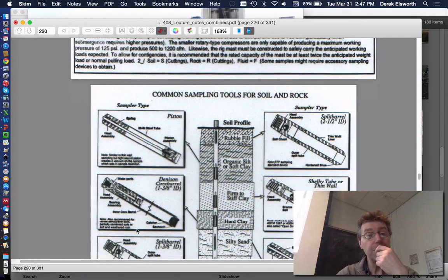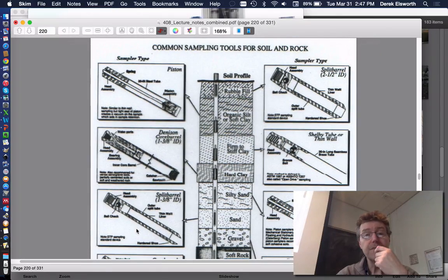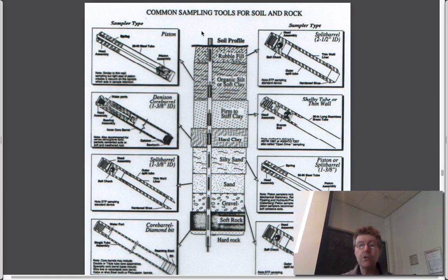So the whole motivation of that hole was to proof test a tool, which we'll see as we go through some pictures. A tool that was going to be used offshore in the Gulf of Mexico to be taken down a big rotary petroleum hole and to be advanced beyond the hole with a little pencil-like probe on it that would measure the pore pressure maybe 2 or 3 feet ahead of the bottom of the hole in soft Gulf of Mexico sands, which are what the reservoir rocks are there. And to be able to use that to be able to predict pressures.